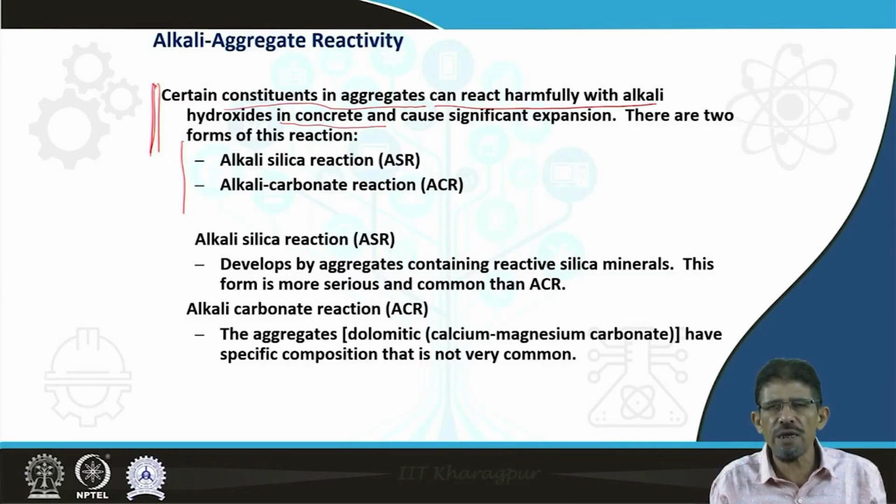Alkali silica reaction has more effect because the varieties of aggregates belonging to igneous rock, metamorphic rock, and sedimentary rocks mainly fall in the silica containing category. However, limited limestone deposits show less impact of alkali carbonate reaction.